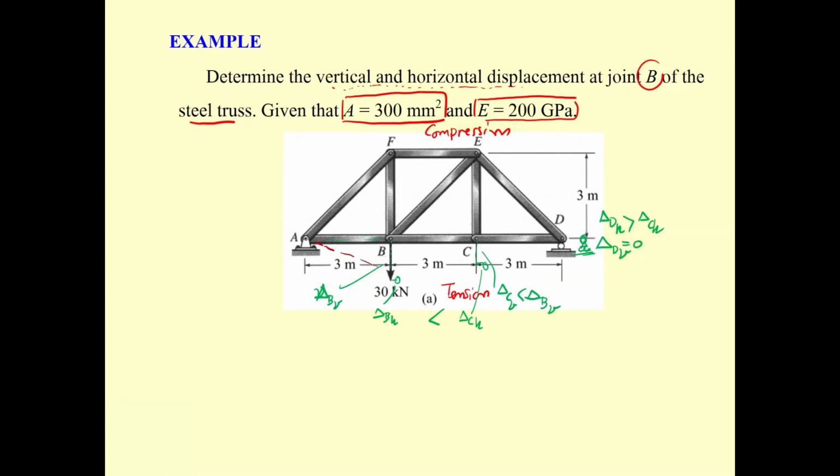Then we sketch the deformation. Put the ruler and sketch a straight line linking the joints. And then you should get this for the draft of the bottom chord. And then for the top chord, it's supposed to be the same downward and horizontal. Just take this one.